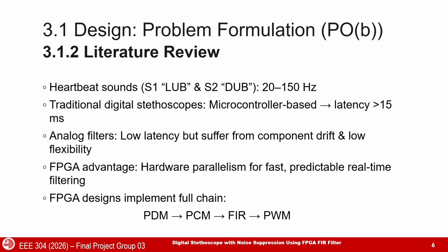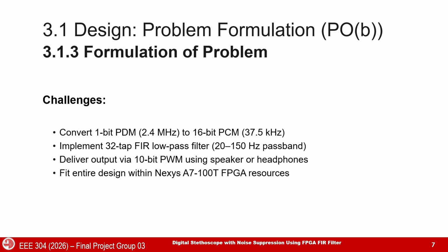Our system processes the signal through a full chain: PDM to PCM conversion, then filtering, and finally PWM audio out. However, there are several challenges, such as converting high-frequency PDM data to 16-bit PCM, designing a 32-tap FIR filter, and filtering everything within FPGA resource constraints.